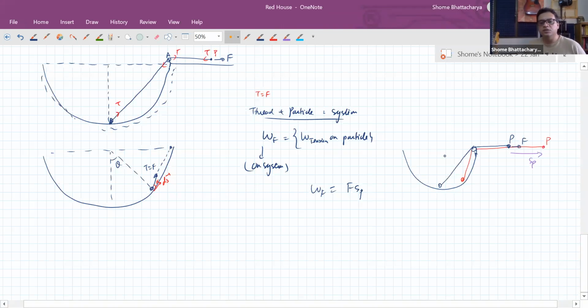Okay, so when our angular position is changing from 0 to some general value of beta, we have to find how much thread has been pulled. So if this chord length was L1, and this chord length is L2, then we can see that the displacement of the point P is L1 minus L2. Thread length conservation, no? So all we have to do is calculate geometrically. L1 we can see in this diagram, this is L1 from here to here. So it is nothing but R root 2.